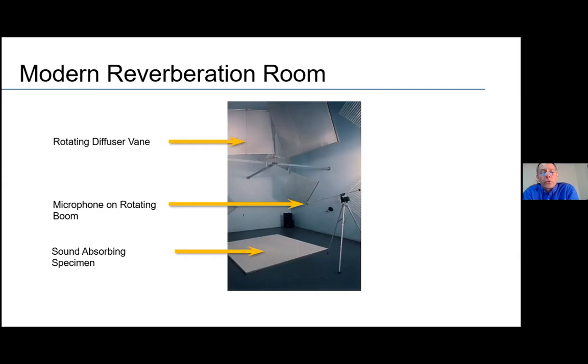And basically what you're trying to do with those is disrupt the noise reflection paths so that you don't get what's known as standing waves that can get set up in a room, especially one that is perfectly rectangular where you have a lot of parallel noise surfaces. You can get a situation where the noise just keeps bouncing back and forth from wall to wall or ceiling to floor, and you can actually get the noise level to add as the waves pass each other as they're transmitting back and forth, and you can set up these standing waves.